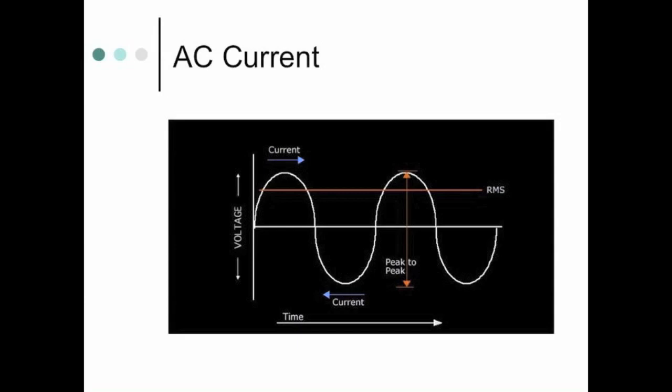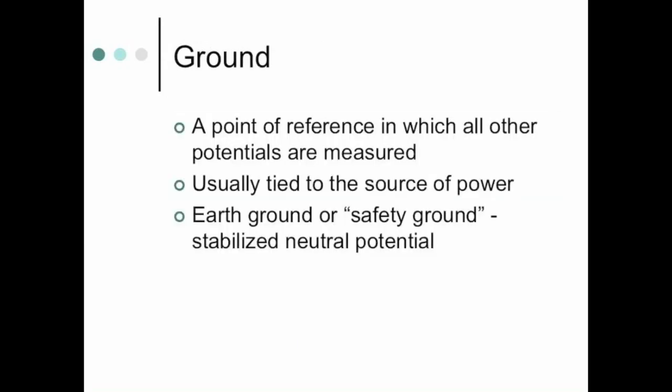Now there's one key issue that we didn't discuss in terms of electronics that I think is very critical. For example, we discussed what potential is, but it has to be potential relative to what? Relative to a baseline of no volts. If we're talking about volts being a potential difference in the amount of electrons that it would make move, we have to have a reference of what 0 volts is. That's where we get to ground. It's called ground because it's 0 potential. It's our reference potential, and it's usually tied to Earth, believe it or not.